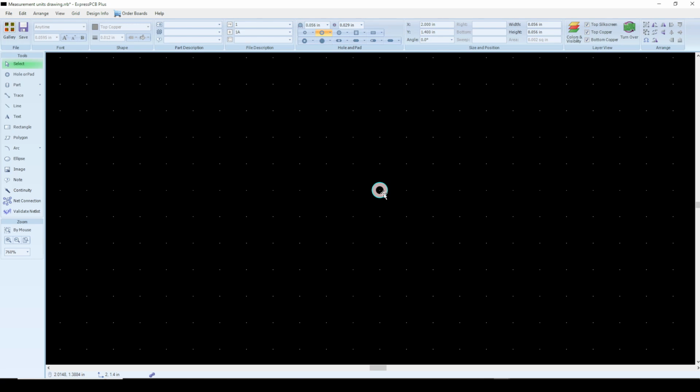And just to drive the point home a little bit more, let me open the menu one more time. And I'm going to change to 0.025. And that'll mean there are 4 snap points now. So when I move it, 1, 2, 3, 4. Now, I normally work with only 4 snap points between my grid points. I find that seems to work out best for me.